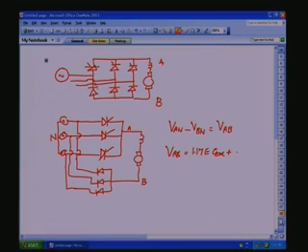So, this will be equal to 1.17 ERMS, because for the diode alpha is equal to 0, cos alpha is equal to 1. So, the net voltage for the semi converter is equal to 1.17 ERMS into 1 plus cos alpha. Okay.